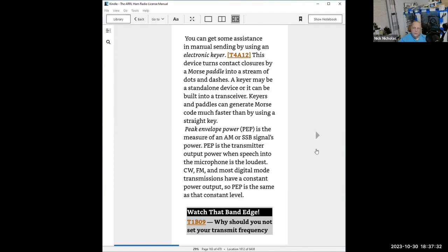Understand that in Morse code, generally, the first 50 years was manual keying, and they had a device that we now refer to as a straight key. And later, they had a thing they referred to as a bug, which had a flying contact, which would make the dots, but you still had to manually make the durations of the dashes. An electronic keyer is an electronic circuit that has basically two switches. One switch makes all dots, one switch makes all dashes. So you hook what's called a paddle to it. You hook that up to the radio, although some radios have them built in. And if you're sending Morse code, you can send dots and dashes by pushing one side or the other, which is basically making one switch or the other. All right.